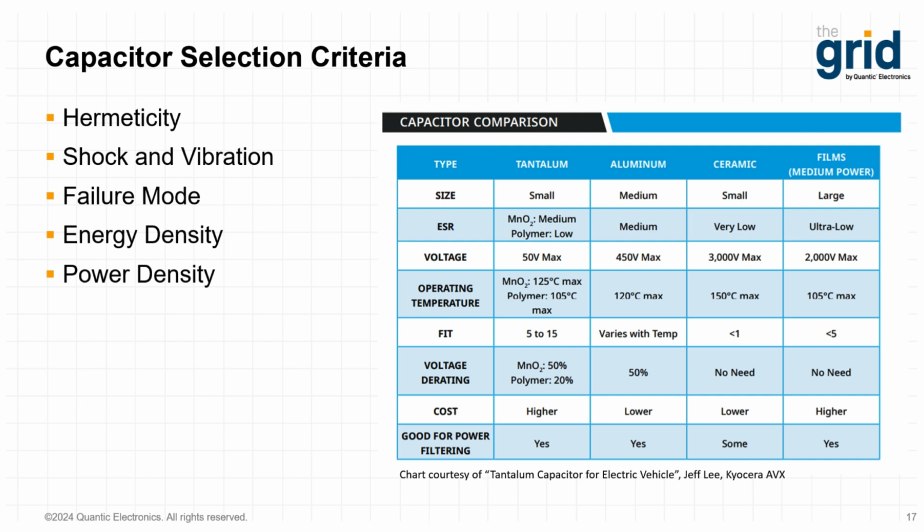So it's really important to pay attention to the capacitor's temperature range, safe operating range, during capacitor selection. Some capacitor technologies have significant performance variations as their temperature changes. For example, some capacitors have much lower capacitance ratings at cold temperatures and can lose half or more of their stated rated capacitance at aggressively low temperatures. And these aggressively low temperatures are those commonly seen in high altitudes or space type applications there.